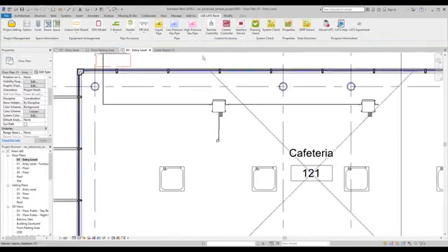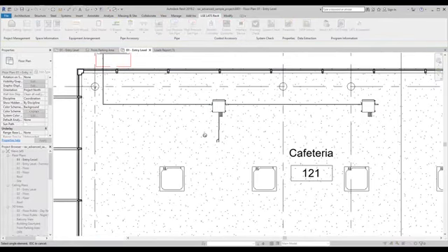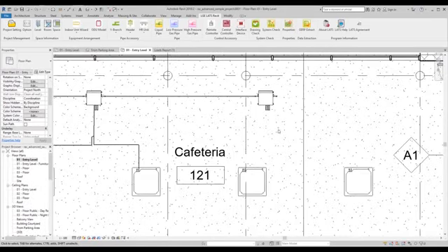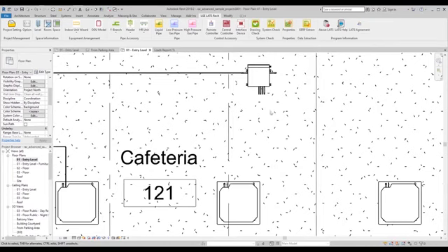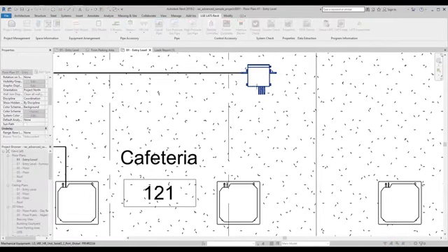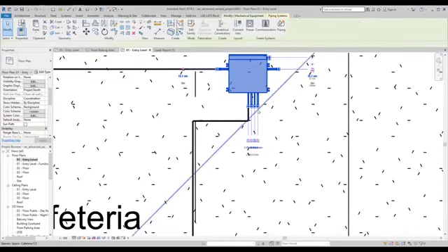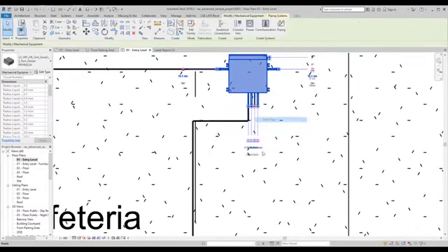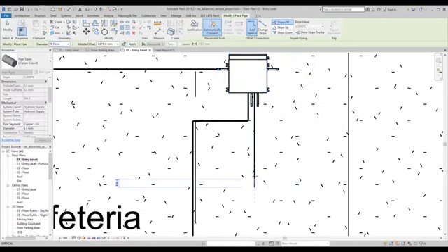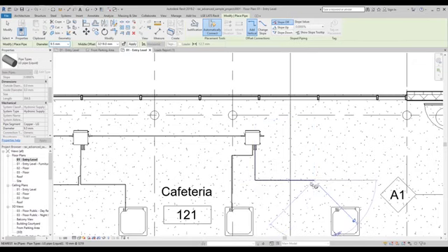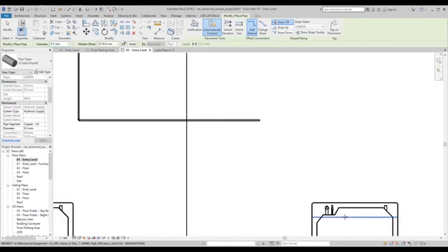You can use automatic liquid pipe connections again for the HR and indoor units. You can manually connect liquid piping by right-clicking on the liquid pipe symbol on the units and selecting Draw Pipe. Make sure the pipe is set to LG Pipe in the properties.